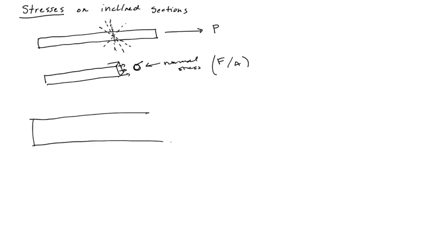It's really just some basic geometry. Let's say we have a cut like that, and just build some triangles here. So we have a triangle there, and we have an angle, let's say theta there, and then if we were to look at the distribution of the internal force, it should look something like this, okay, where this uniformly distributed internal force, the resultant force should again always be balanced by statics.